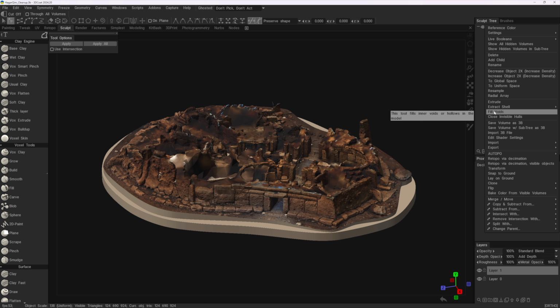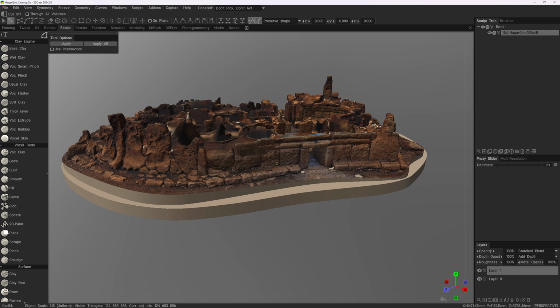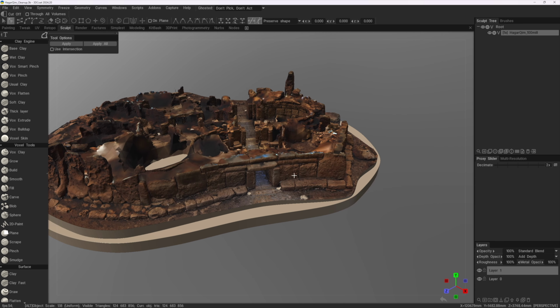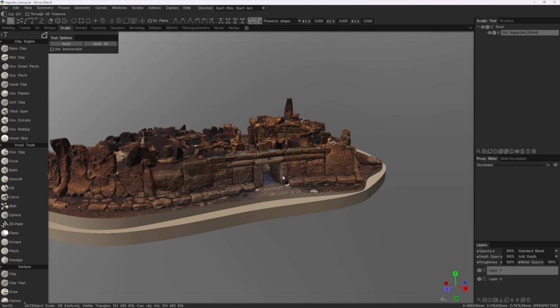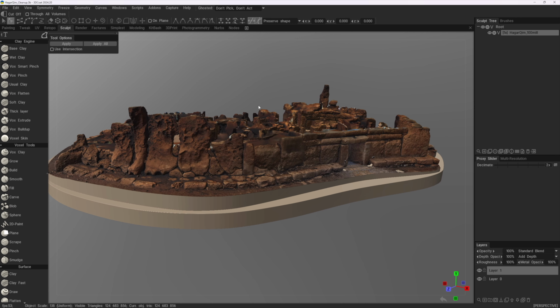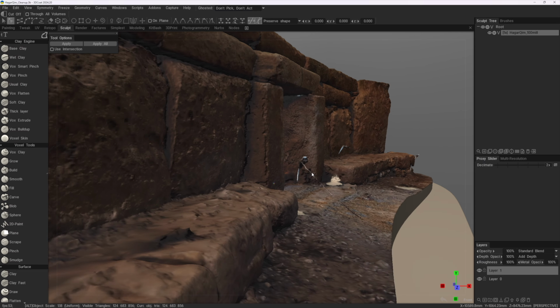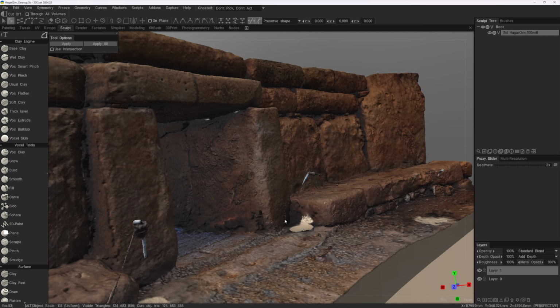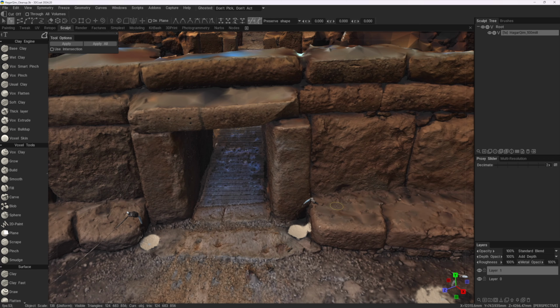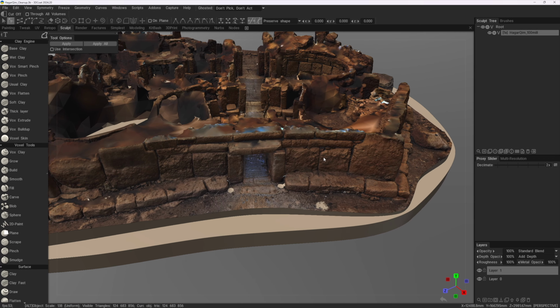So I'm going to do it. I always do it just to be safe. It will not destroy anything if there are no holes or bubbles. It does take quite a long time to fill the voids when you got a huge mesh like this, but it's done. So as a final thing, before I export it, I need to get this into surface mode so I can remove these floaters here. This is something I can't do in voxel mode. There is no way to just click and get rid of these, so I need to convert it.